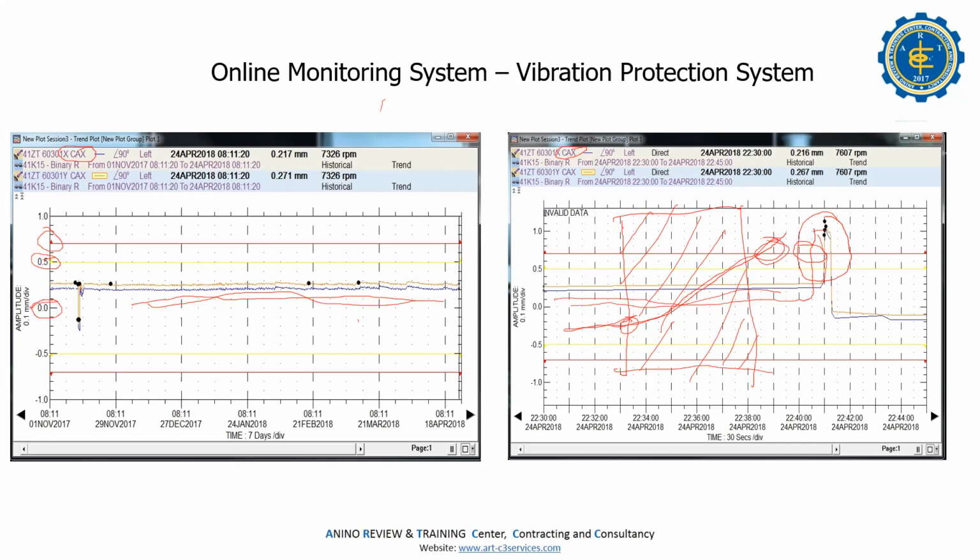Every day, I knew there was some rotating looseness in the bearings. I can't do much because there is already too much rotating looseness, and there was a drift in the fan, because the fan has more vertical vibration than horizontal.